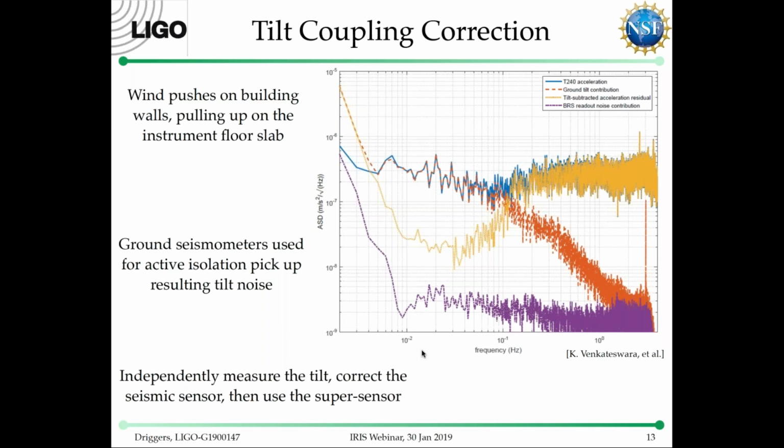If we think of a seismometer as a mass on a spring, if there's true horizontal motion, the mass will move back and forth on the spring, and we'll be able to sense that mass's motion, and we'll call that horizontal motion. However, in a gravitational field, like on the Earth, if the seismometer is instead tilting, then the mass will still extend or retract the spring.